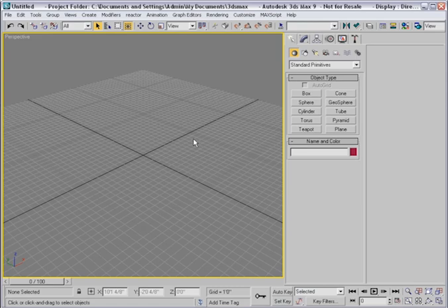However, a lot of the objects that I might have lofted in the past, today I would sweep with the sweep modifier. And the sweep modifier is great at creating objects that have a constant cross-section. But I would use a loft if I was trying to model an object that had a variable cross-section.